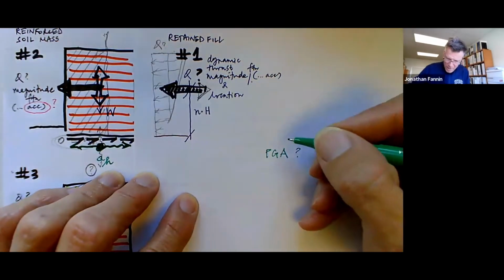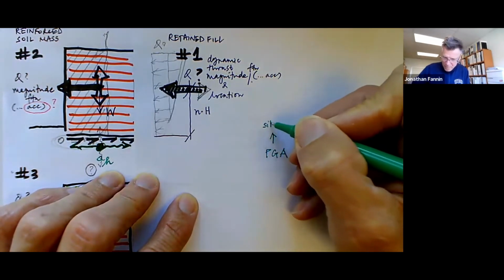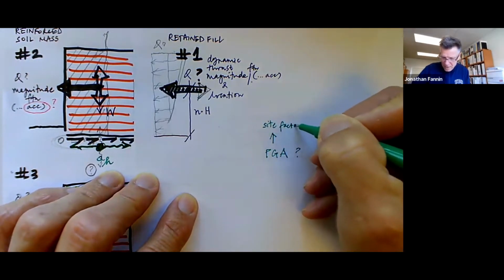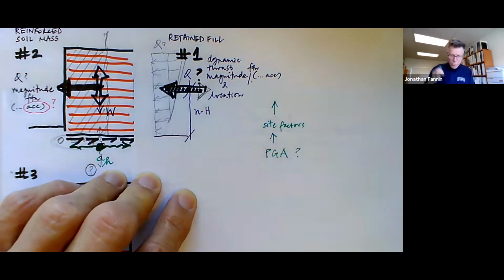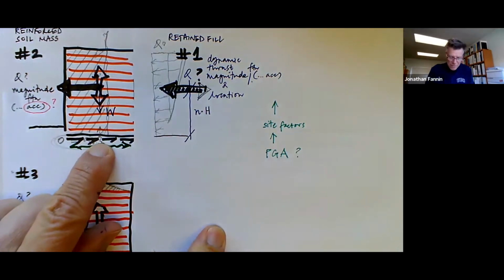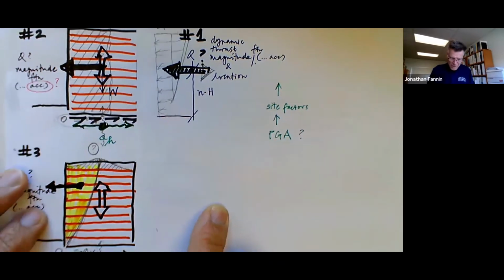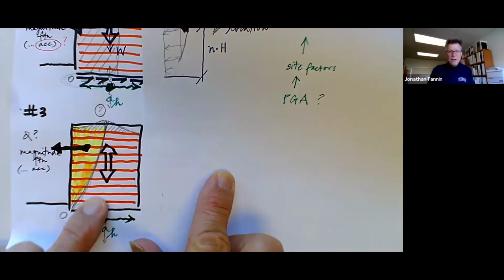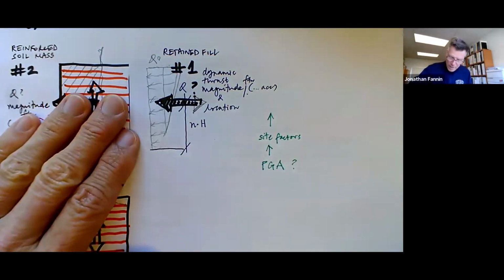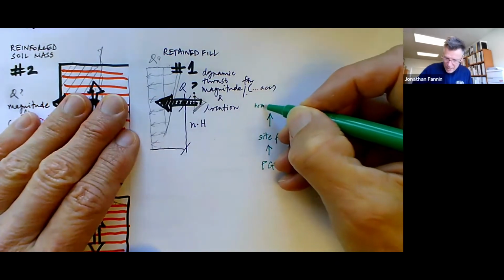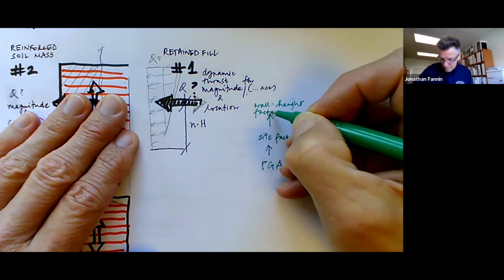And then we may modify that by site factors. We might be invited to address site factors. And then we might be invited, as we move from the acceleration at the base of the structure to the acceleration at the centroid, to put on a wall height factor.